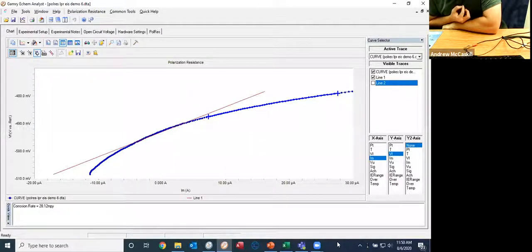For example, compare the potentiodynamic scan that I mentioned before, where we're scanning over a voltage range of 1-2 volts, as opposed to just a few millivolts. That is destructive, and you certainly are going to change the surface of the material. But the LPR, I don't see as a truly destructive technique, as opposed to a lot of the other experiments where you vigorously polarize the surface, as opposed to just enough that you can get a measurement.